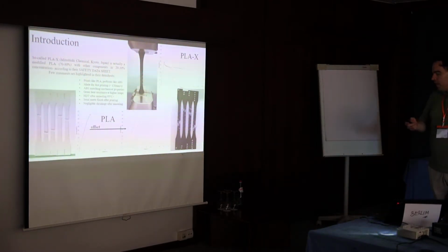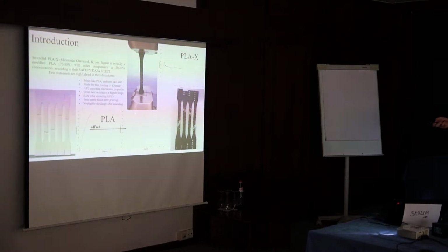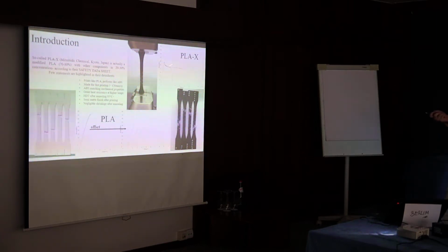Now concerning PLA and PLAX, the PLA material we have fractures in a so-called quasi-brittle manner. This is how the stress-strain diagrams look for this material. All 5 specimens had similar results, so there is good repeatability. But the PLAX material has lower UTS but much higher plastic deformation than the original PLA.